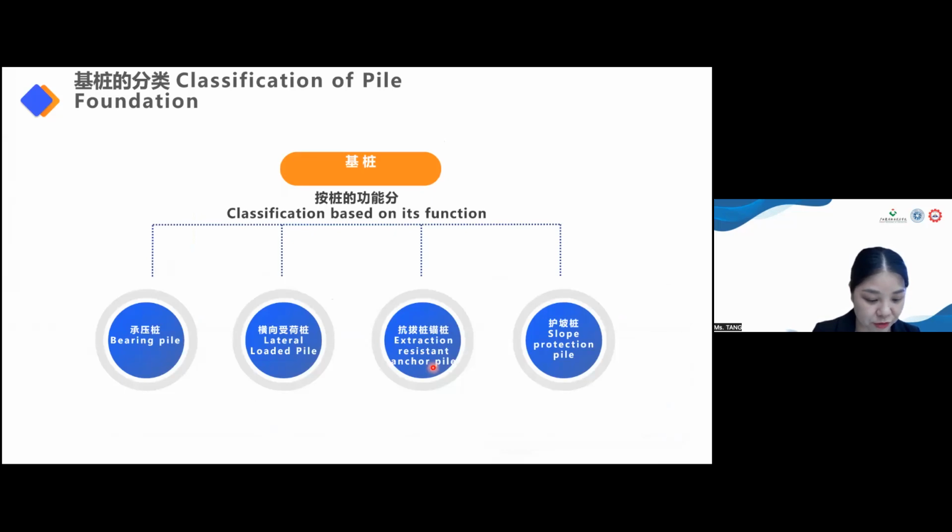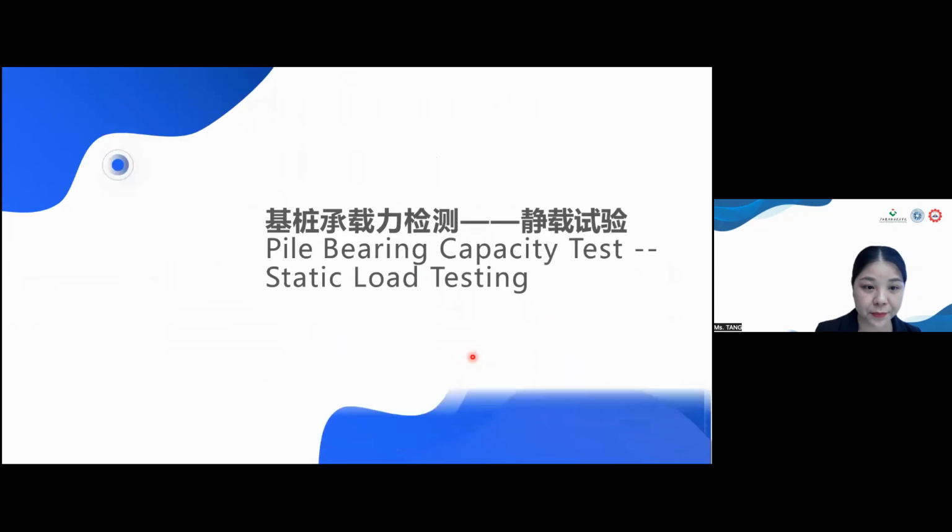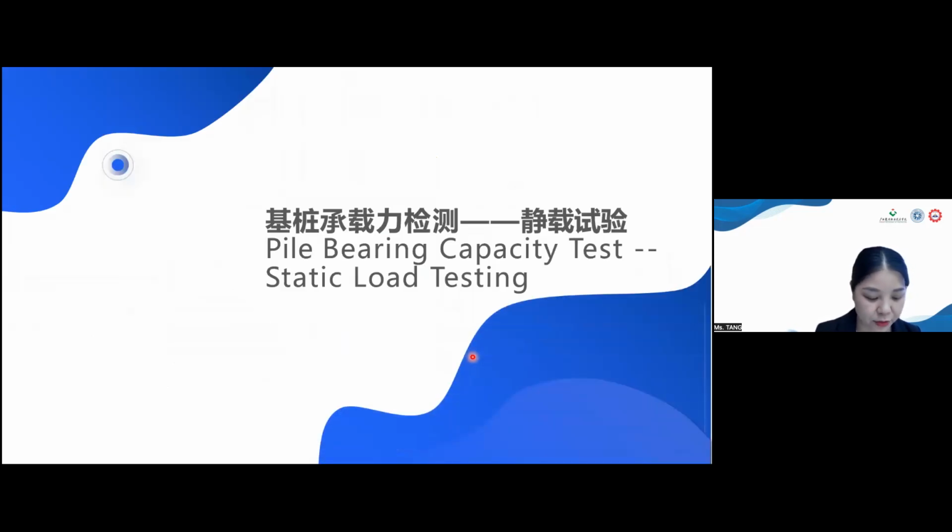According to the function of pile, foundation pile can be divided into bearing pile, lateral loaded pile, uplift resistance anchor pile, and slope protection pile. According to the production and construction method of pile, foundation pile can be divided into driven pile and cast-in-place pile. Next, I will introduce part 2, pile bearing capacity test, static loading testing.